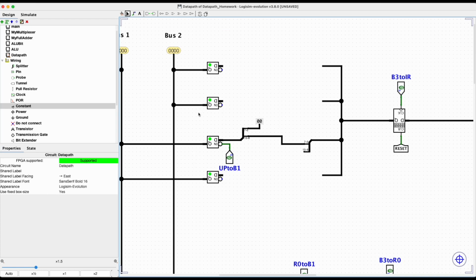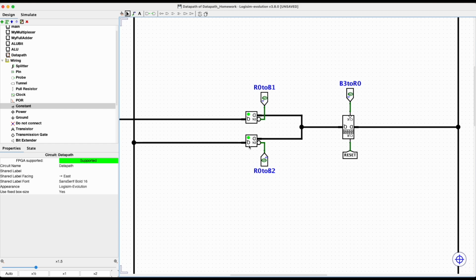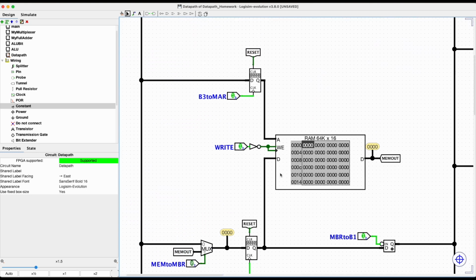And then right here, there's the unsigned immediate instruction, and you can look in the reading, there's probably the OR immediate, or ORI, instruction that tells you how you take the immediate value out of the instruction and place it onto this, and what we fill it up with, zeros or something else. So make sure you read that guide to know what you fill it up with. So just finish up that. Of course, you need to finish up all of the other registers. I only did one register here, but other than that, you should finish it all up.